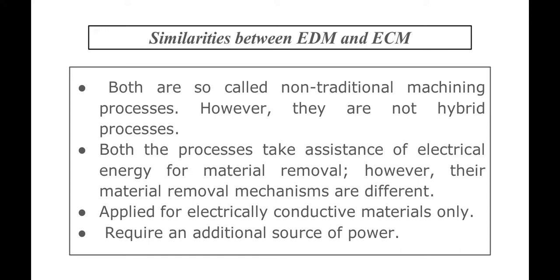Now let us discuss various similarities between ECM and EDM. The first point is that both EDM and ECM are so-called non-traditional machining processes. However, they are not hybrid processes, and both take the assistance of electrical energy for material removal. Their material removal mechanisms, however, are different. Then, they can be applied to electrically conductive materials only. For non-conductive materials, a coating strategy can be adopted in some cases, but